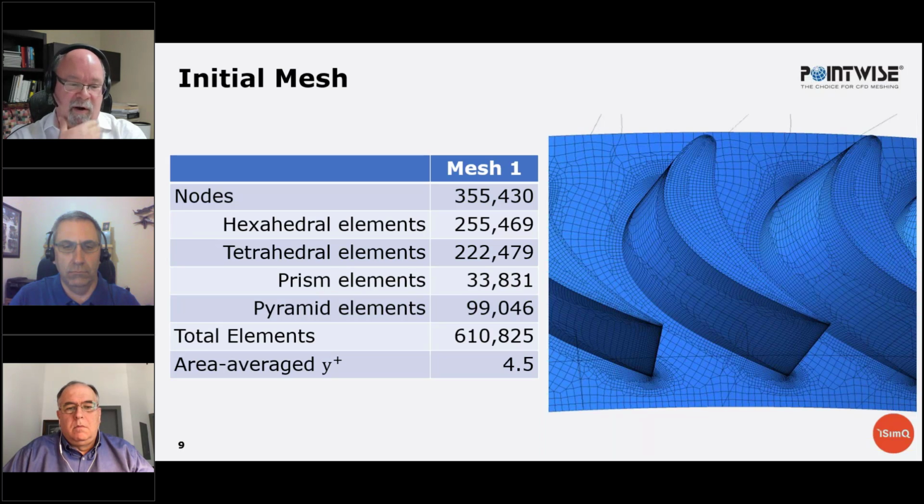And I think an important point here, leading back to some of the quality and so on that Nick was talking about, is that we're going to rely on the mesher to generate the boundary layer resolution. No one needs to run a CFD solver to know the size of the boundary layer and the thickness of the boundary layer. We know that from the Reynolds number. And so why not put that in right as a starting point in the mesher? We shouldn't be relying on adaptation to automatically produce our boundary layer mesh.